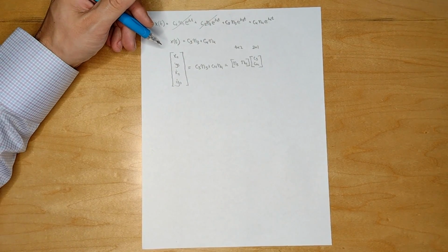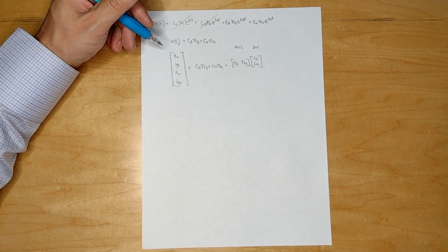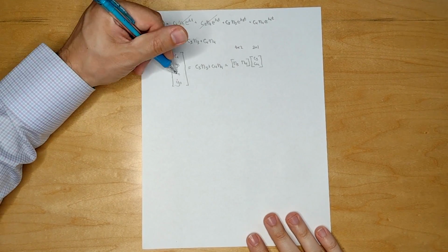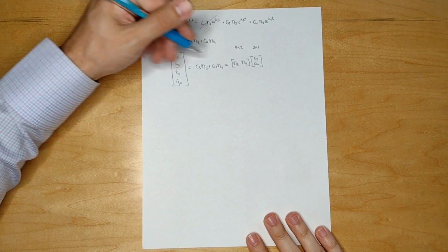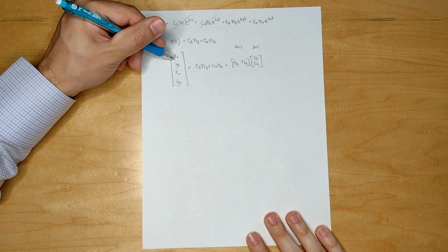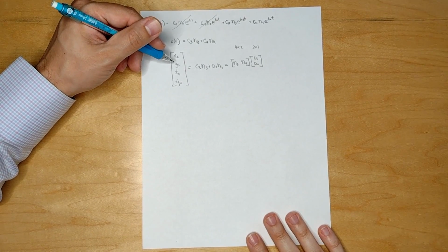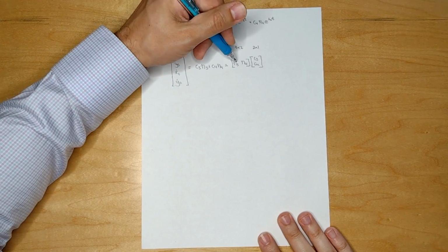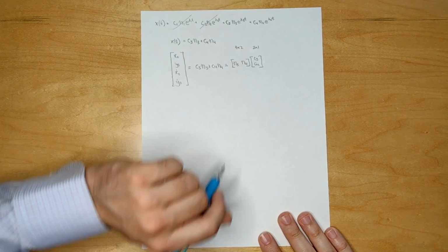So here, like I said, we have a system of 4 equations and 4 unknowns. These are our unknowns: the initial velocity and the c3 and c4 values. The initial position we're going to dictate. We're going to say that we want to start, say, a kilometer away from the Lagrange point. And the eigenvectors, we're going to find those in a minute.